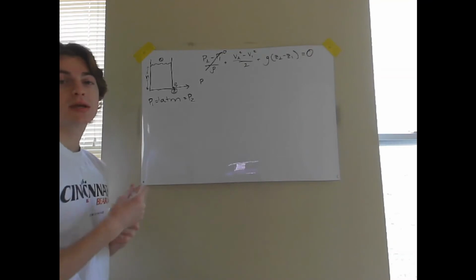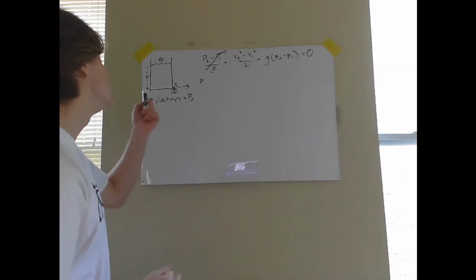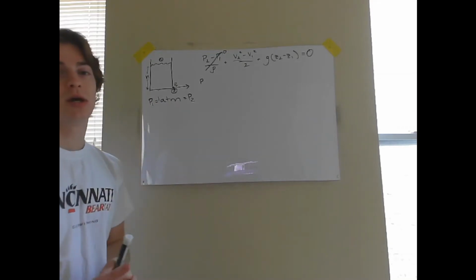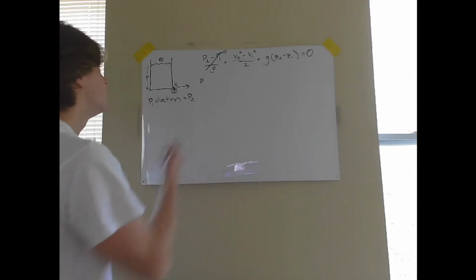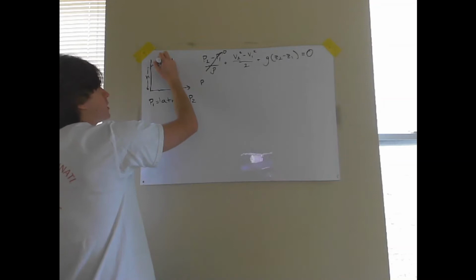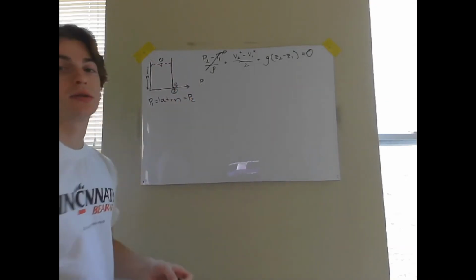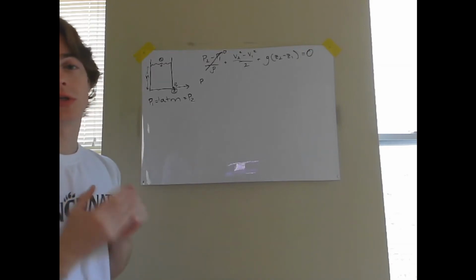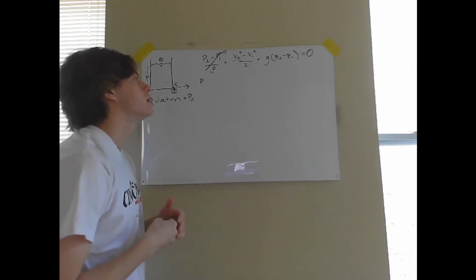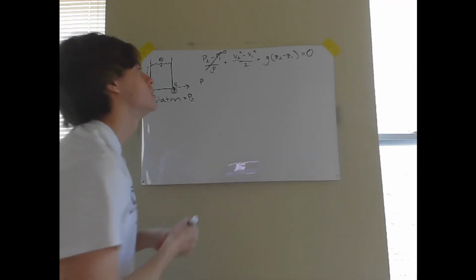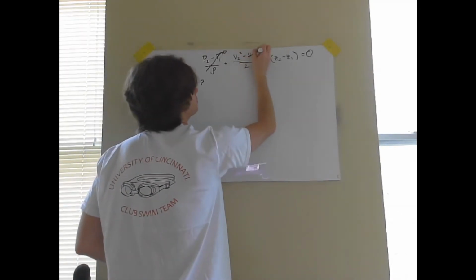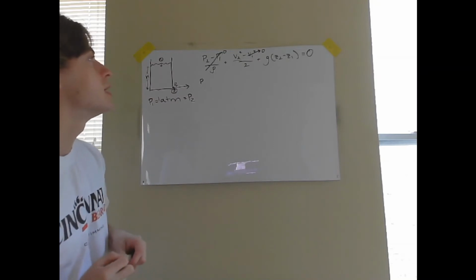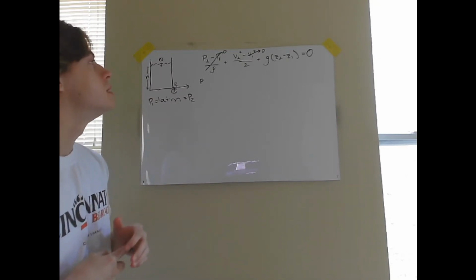Well, the tank has a very small hole, so the volume that's leaving the tank isn't going to change the height of the tank too much. And so the velocity of this top level moving down is going to be extremely small. And in this problem, we're just going to say it's negligible, just to simplify things a little bit. So V1 is going to go to 0 because, again, it's super small, and it's not going to change our equation too much.